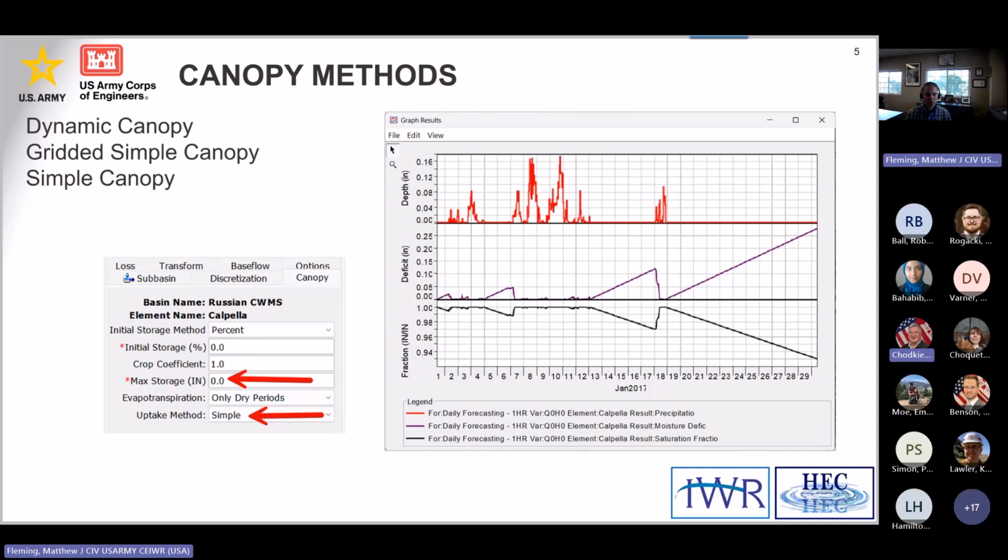And you get to choose. If you want 3 layers in linear reservoir, then you can have 3 layers. If you want just 1 layer, you can choose just 1 layer. Then you can define, based on how much infiltrates into the soil, what percentage of that infiltrated water goes to those different baseflow layers.